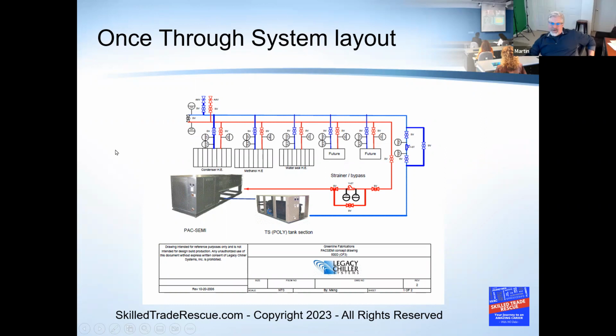Yeah, the other one, I love talking shop. The other one on these systems, we had this happen more on once-throughs, is if you make any change along any one of these valves right here, right? And you don't play around with this bypass. A lot of them don't even know it's there. A lot of times these are put in places where nobody knows they're there. But if you make any change along here, what does that do to your net flow rate going through your evaporator?